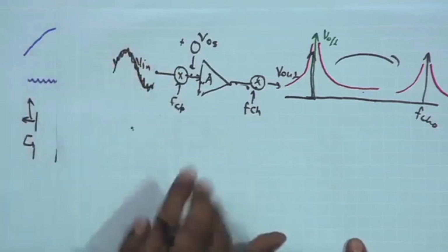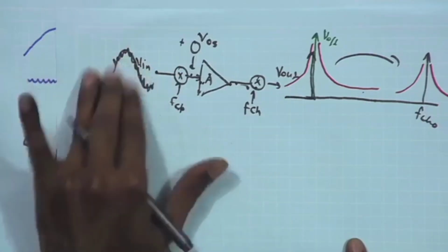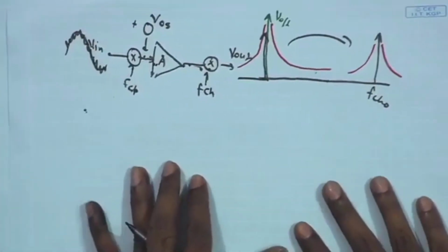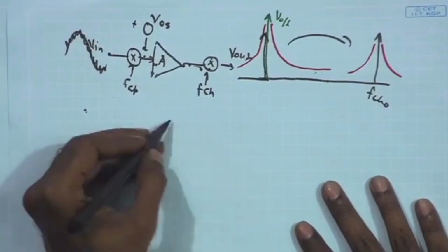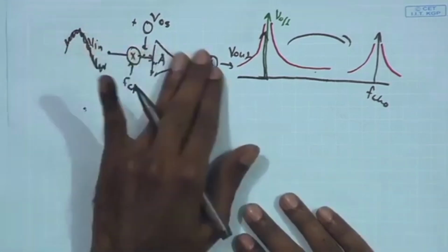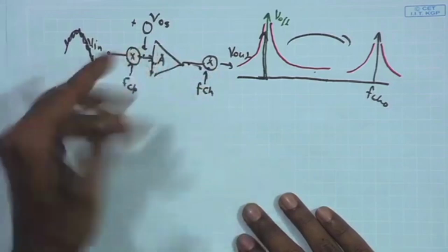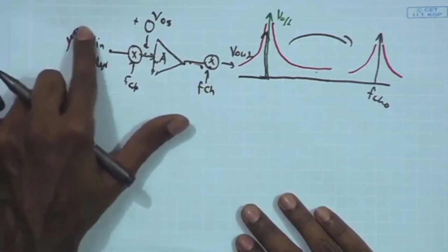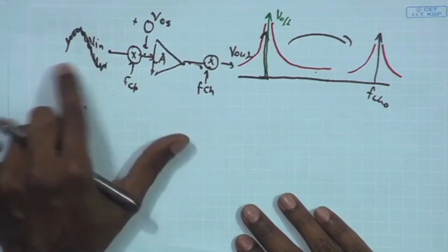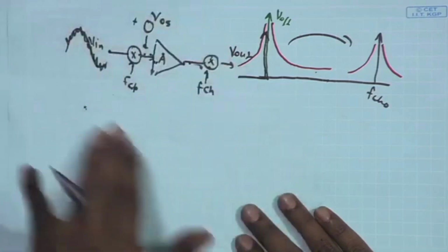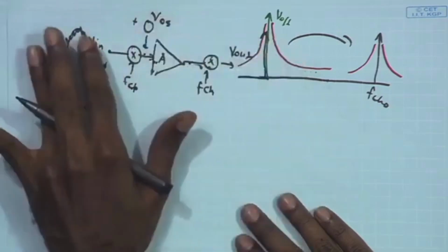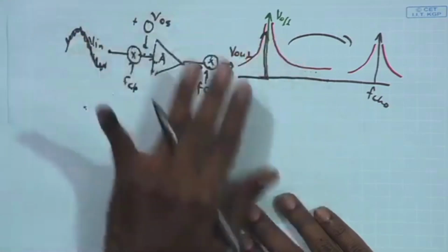And for that we need to make sure that we have an amplifier scheme which is able to reject this. At high level, that scheme can be represented as a negative feedback loop for this low frequency signal. So, the target is that we add a negative feedback loop, where this low frequency offset, or the low frequency dynamic offset, is experiencing a strong negative feedback, but the input signal is not experiencing that feedback.